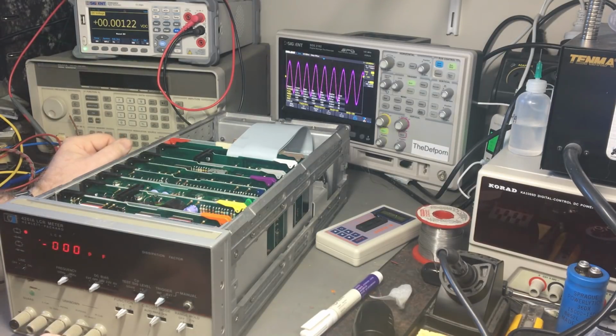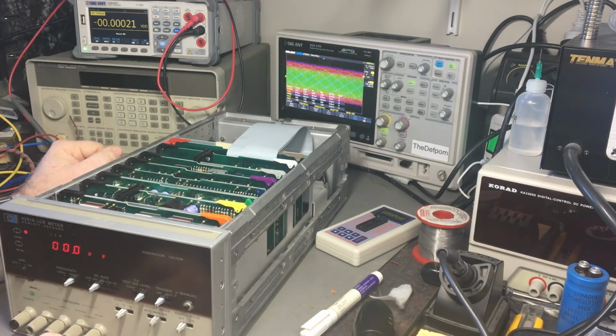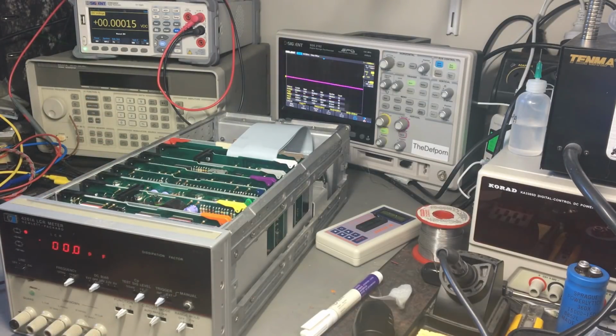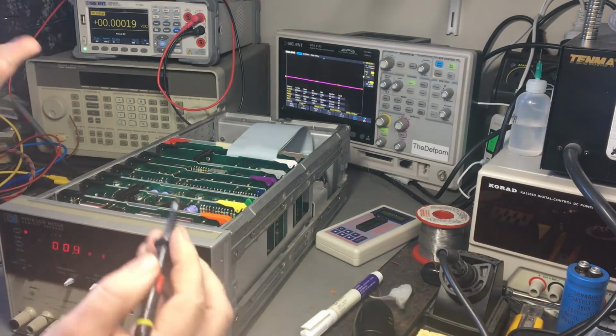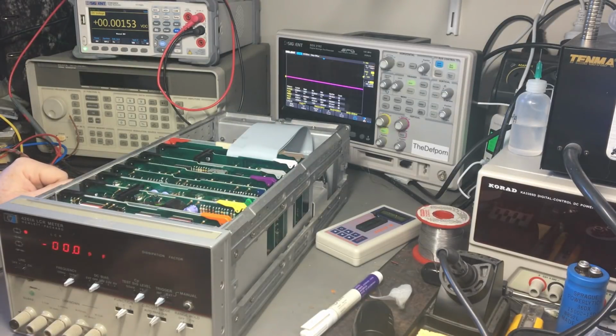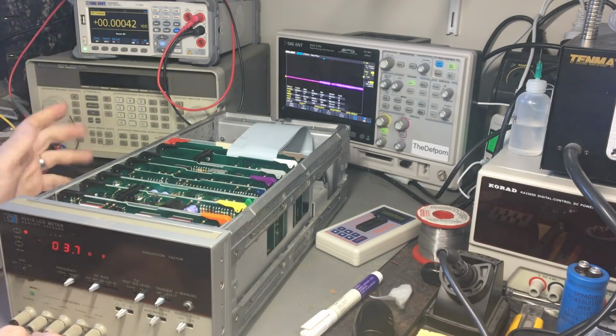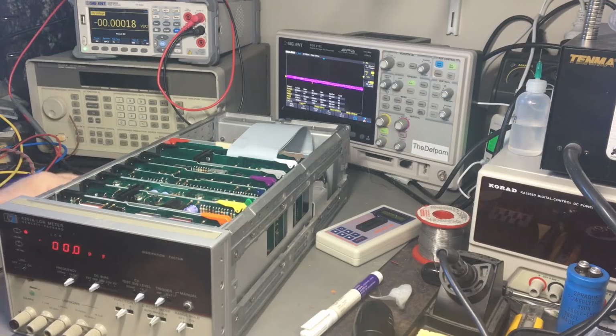Strange. Anyway, that's really 920 millivolts. If I change the frequency again, about 916 millivolts. So that's slightly lower than what it says. But then I don't have an earth probe on here, so maybe that will change if I do that. But those seem correct.